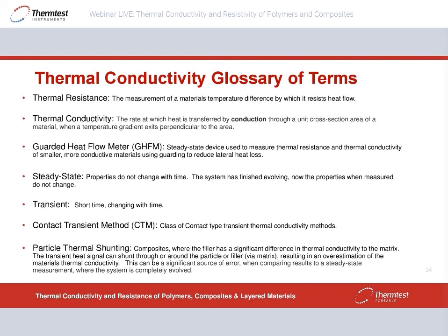About carbon foam. So sure, it really falls into that carbon being, I guess, a conductive matrix with pores. So one of the examples I gave fits this, which is, if you want to think of it, an insulative component, and the heat is really going to shunt around for transient methods. So you really want to measure that through resistance. If your sample size fits this method, the sample size for a guarded heat flow meter is 2-inch diameter, this would be an extremely valid method, and what this method was designed for is your type of sample. So it could be done.